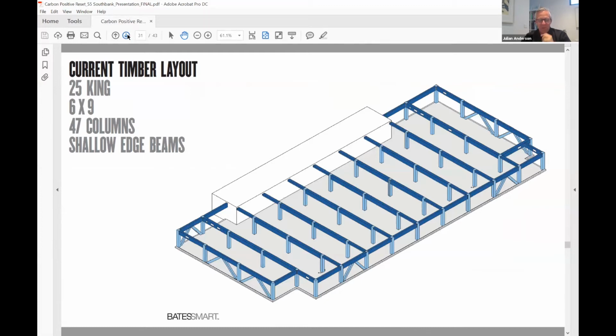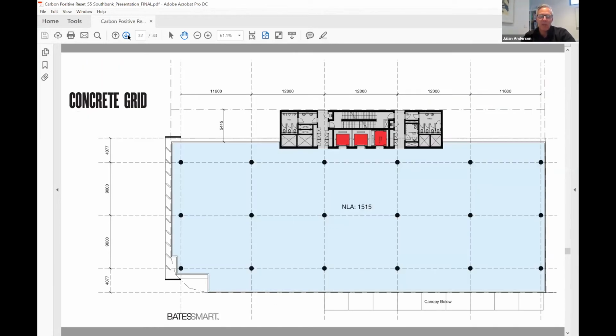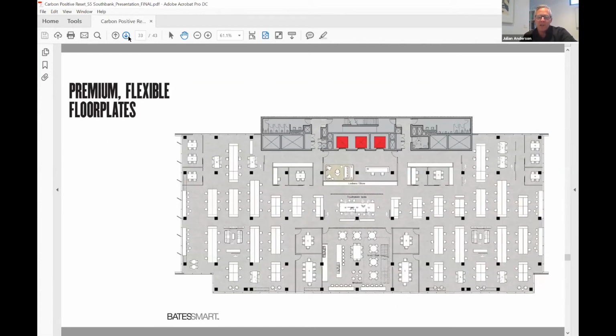There has been a shift, we think, in office markets to say we don't necessarily need column-free space to have a great space, and the shorter span does help deal with vibration. And the timber columns in this instance are generally about 550 mil square, and you compare that with a traditional concrete frame structure, you typically start with 9 by approximately 12 metres. The timber grid is quite different, but we don't think it limits flexibility.